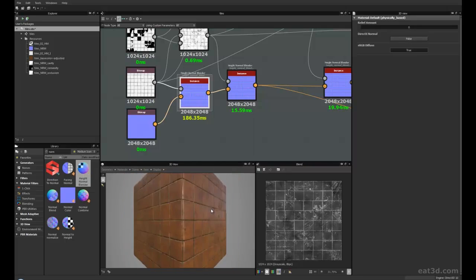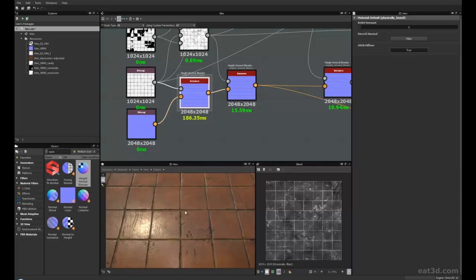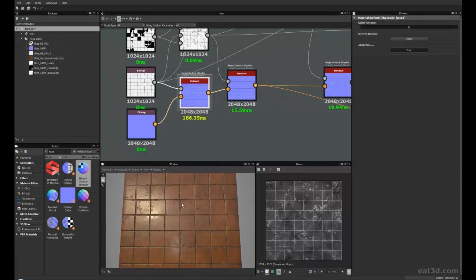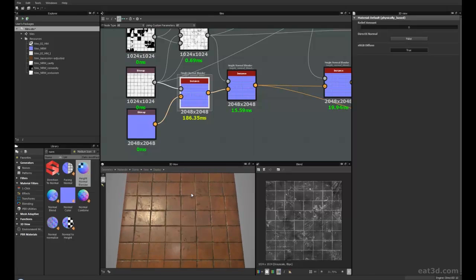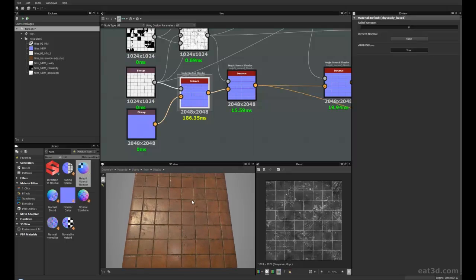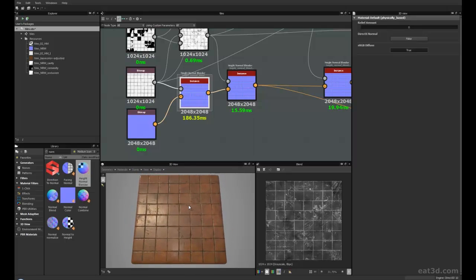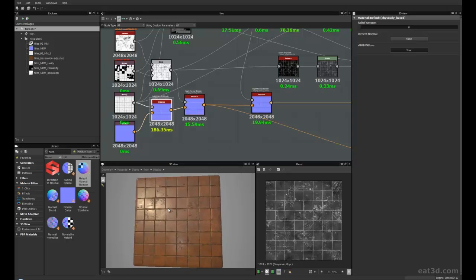And because the Y is in a positive, it's OpenGL, so there you'll see that it's correct. If in doubt, click that, and you'll be able to tell when it's correct. But normally, when I bake stuff out, I normally bake it out as OpenGL. But I do know that CryEngine and Unreal Engine 4, they use DirectX. So just to make you aware. So right, by that point you know that your 3D view's alright and it's correct.